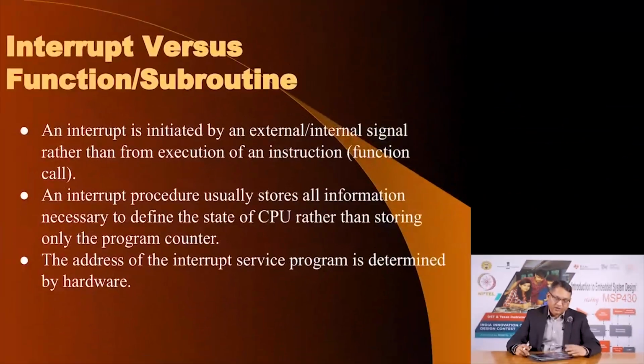Now, how do you handle interrupts? As I mentioned, your main program that you were running would be suspended and you would execute a subroutine, and therefore, it may appear that performing a response to an interrupt is like executing a subroutine. Indeed, it is, but it is different from a conventional function or subroutine.